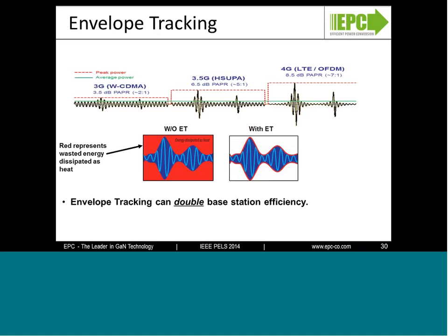So when we talk about point of load converters and fighting for a couple percentage points of efficiency, you see the ability of GaN in these emerging applications to provide solutions that just weren't possible for silicon, where we can do things like double the efficiency, talking about 25 to 30% as opposed to a couple of percent. So you can see the potential and the desire to use GaN inside these emerging applications.